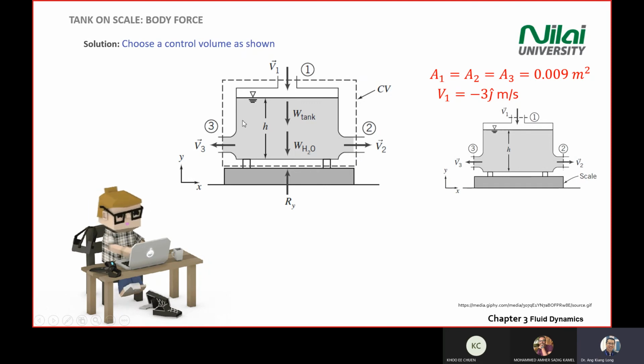Okay. Then after that, you draw the free body diagram. I mean, you consider a free body diagram with the control volume. After you copy the diagram into your answer sheet and draw the control volume, you score 1 mark for the control volume. Next, you will see the question asks you to draft a free body diagram for your solution. So what do we mean by free body diagram? Meaning you put in all the forces that you can see or predict inside the control volume.